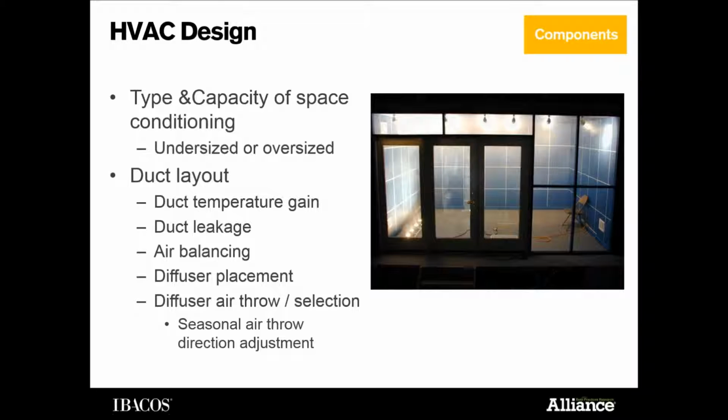Air balancing, this is one that really bugs the hell out of me. And I think Tim too. So Tim, from the commercial aspect, you see balancing dampers everywhere. Absolutely, and it literally does drive me nuts when I came into the residential side to see the lack of that in many cases. So we're going to focus on that. Yeah. So we always try to design a duct system with some type of balancing control, so we can make sure that those rooms are getting the right airflow that we design in that Manual J and Manual D calculation.